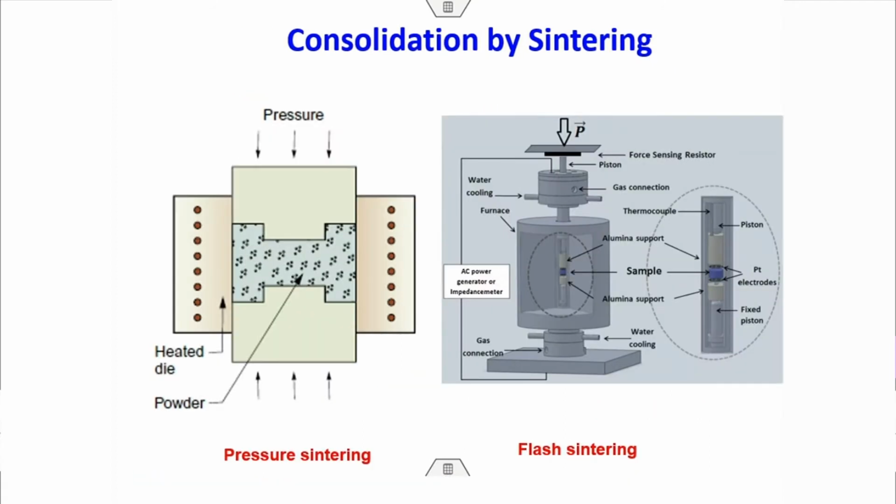As I said, these techniques produce powder, so you need to consolidate them, and that can be done using flash sintering or spark plasma sintering. These are nothing but routes known as field assisted or field activated sintering techniques.